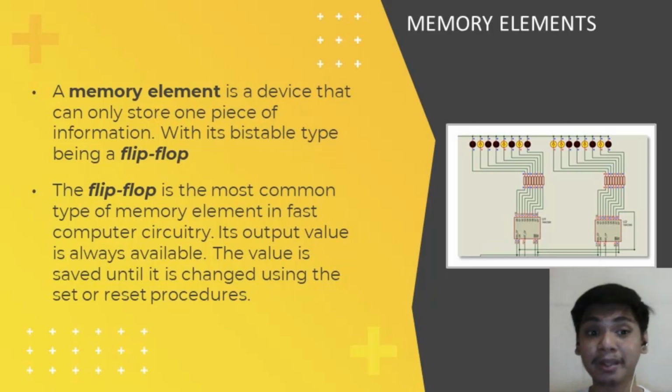After introducing an element, let us now know more about the actual memory element. It is a device that can hold at most a piece of information, and a common type is the flip-flop, which may consist of logic gates, such as either a NAND or a NOR gate loop, used to implement a clocking function depending on the type of the flip-flop.